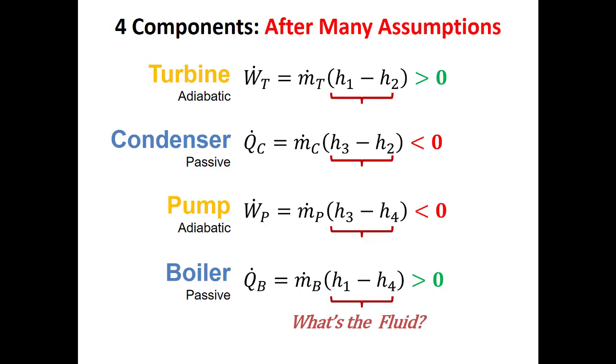But when you get to this point, you'll have symbolic solutions that'll depend on delta H in this case, or maybe delta S in some other cases. So you'll have to ask, what's the fluid? And as we move through different cycles, the cycles will be differentiated in part by what the characterization parameter is, and in part by what the fluid is. So if we're talking about a Rankine cycle, we're talking about water typically as the working fluid, although it could be any working fluid that's moving back and forth across the vapor dome. And in all those cases, even if you were doing a Rankine cycle with, say, a refrigerant because you were operating at some different temperature, the strategies you would use to find H's and delta H's would be the same.